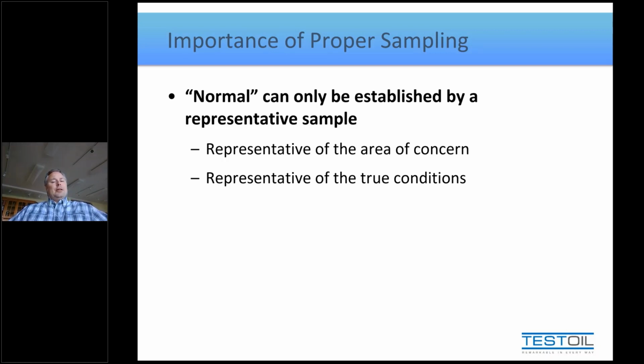Like, do you want to see how dirty it is or do you want to see how clean it is, as an example? But the other side of it is representative in the manner in which it is taken. Are you collecting the first stuff that comes out of the sampling plug, port, valve, whatever you have? Well, that's not going to be very representative. That's not live circulating oil. It's not well mixed. It's not representative of the conditions behind that valve.